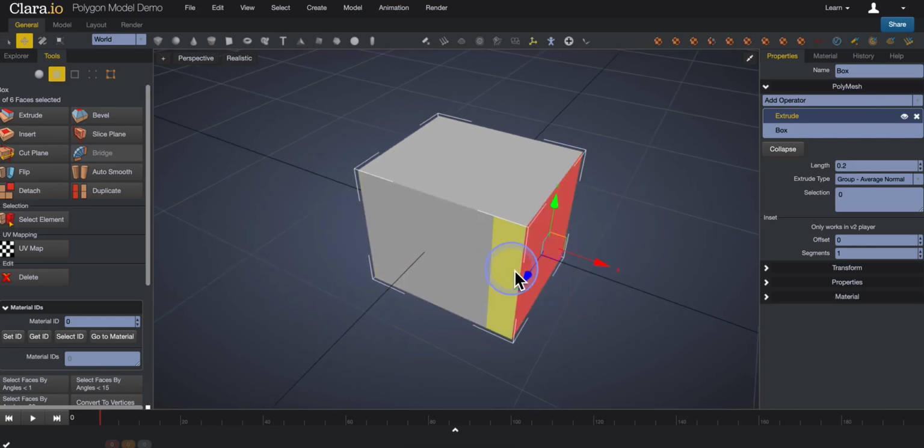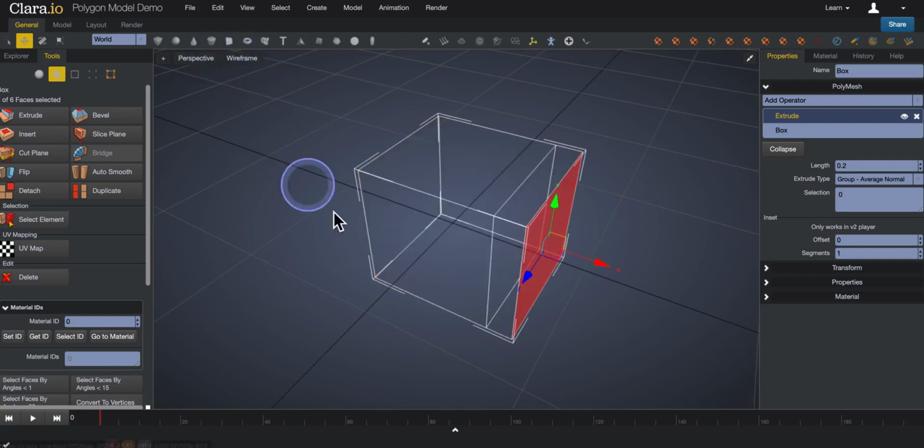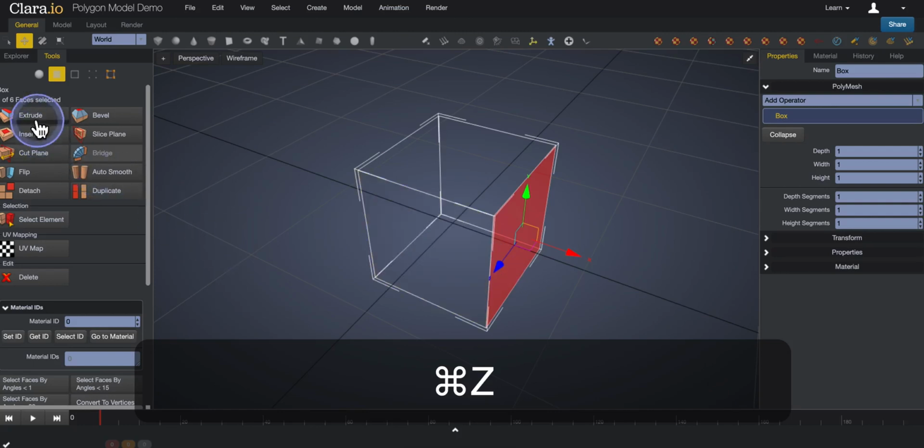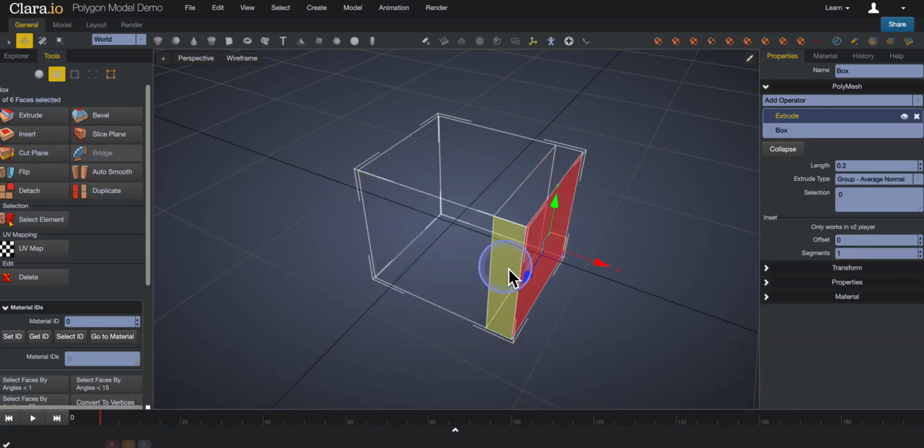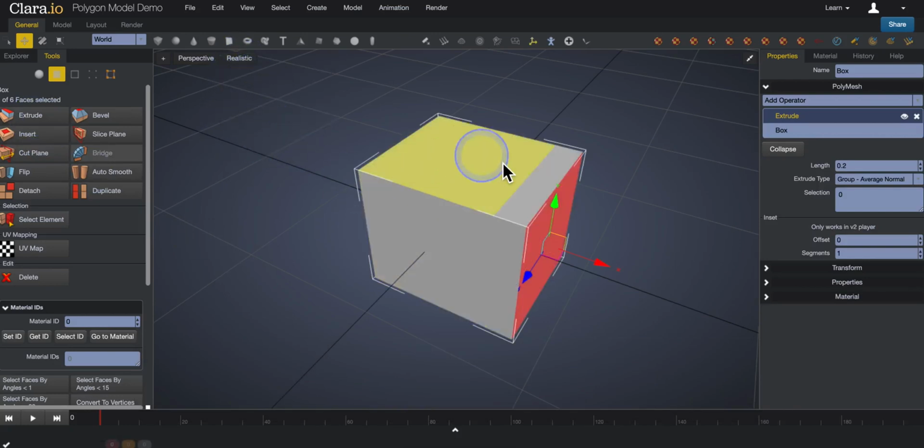If you can't see it like this, what I recommend you do is come up here to the top left. You're going to see these three little menu buttons here. Mine says realistic. If yours says wireframe, then you already see the brand new extrusion. Okay, so I'm going to undo the extrusion, and then I'll do it again so you can see that it just pops out and we get this new section here. Well, I'm going to keep it on realistic so I can see the solid shape, but I'm going to come back up here and I'm going to turn on show edges.